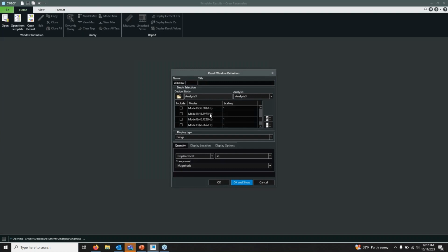And this is going to give us a list of the different natural frequencies that my model is going to resonate at. We'll see the first is at 0.85 hertz. We actually have two there because my model is symmetric, so it's going to give me two results for a lot of these values. We have resonance again at about 5.31 hertz, 14 hertz, 22, 28, 46, 66, etc.